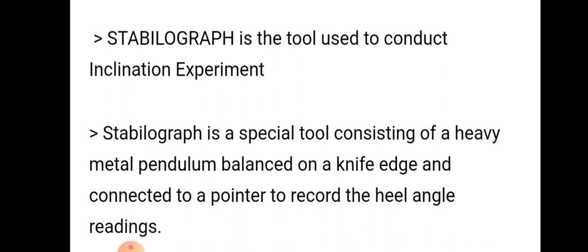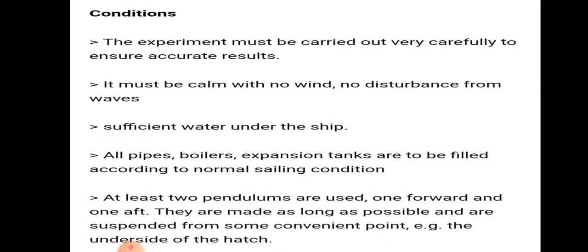Conditions need to be satisfied. The experiment must be carried out very carefully to have an accurate result. It must be calm with no wind and no disturbance from waves. Sufficient water should be under the ship. All pipes, boilers and expansion tanks are to be filled according to normal sailing condition.